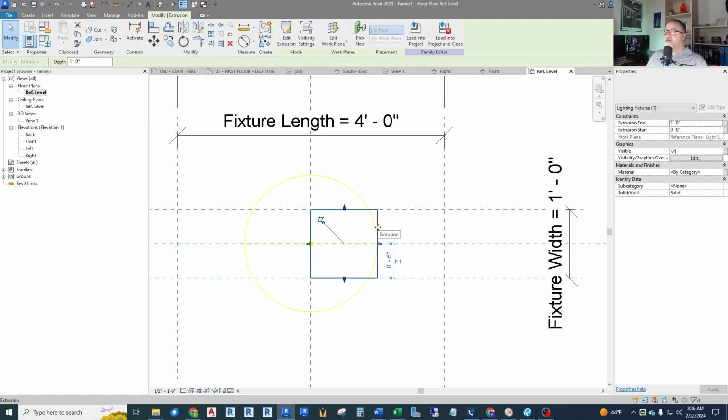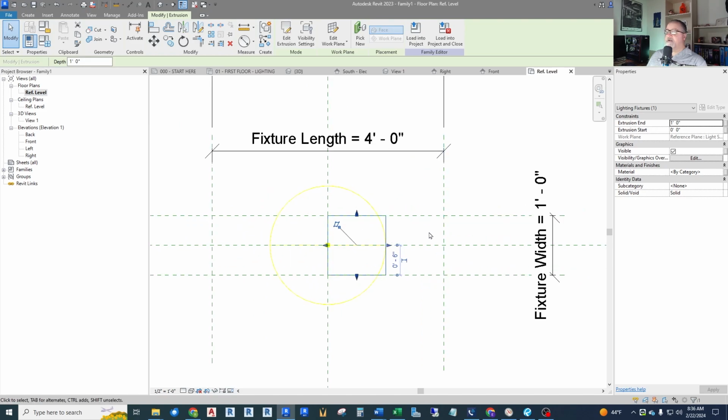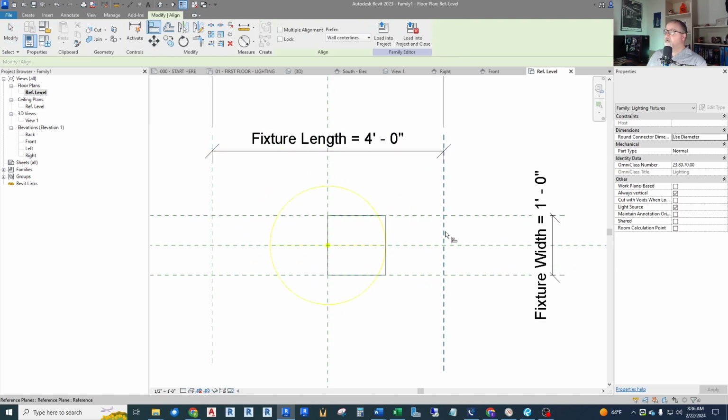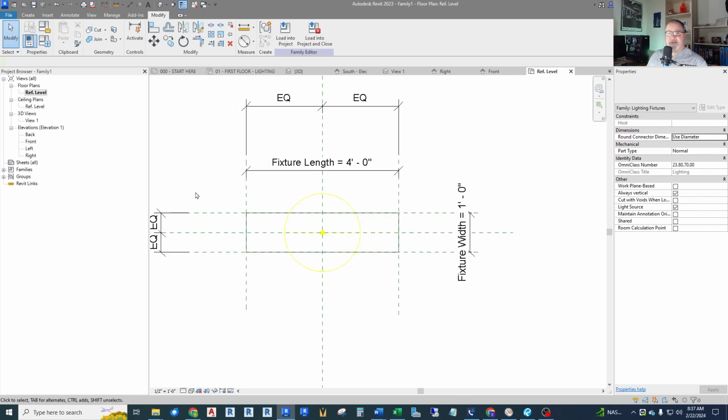I'm going to align this end to the right end of my fixture and align the left end to the left end. So let's just go to the Align tool, align to there, from there, line to there, and let's make sure we tab till we hit our extrusion, and then pin it. Now, that is pinned. These sides are already pinned from my right side view, if you recall, when we created the sketch. So I don't need to pin those. So there we go. Now let us test this skeleton, or flex it, we can call it. We're making it flex, bending it.